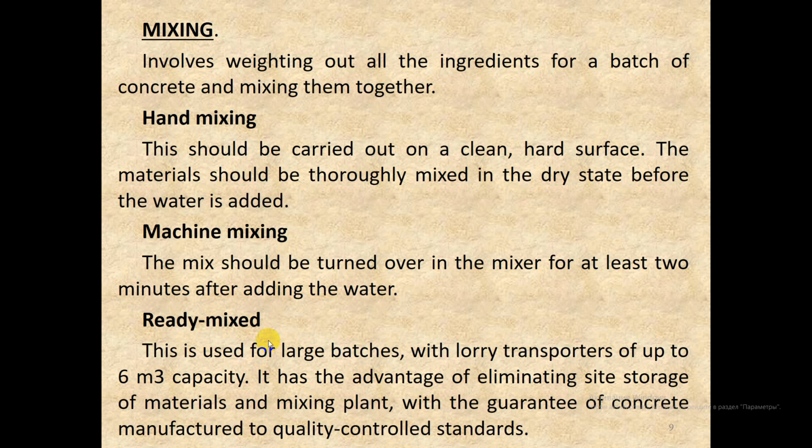And ready mixed is used for large batches with lorry transporters of up to 6 cubic meters capacity. It has the advantage of eliminating site storage of materials and mixing plant, with the guarantee of concrete manufactured to quality control standards.